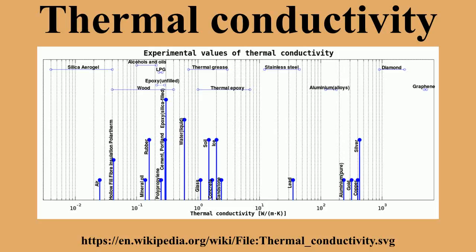Influencing factors. Temperature. The effect of temperature on thermal conductivity is different for metals and nonmetals. In metals, conductivity is primarily due to free electrons. Following the Wiedemann-Franz law, thermal conductivity of metals is approximately proportional to the absolute temperature times electrical conductivity. In pure metals, the electrical conductivity decreases with increasing temperature, and thus the product of the two, the thermal conductivity, stays approximately constant. In alloys, the change in electrical conductivity is usually smaller, and thus thermal conductivity increases with temperature,